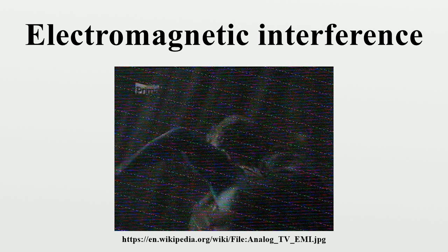Some ICs are designed to have integrated RF filters or a special design that helps reduce any demodulation of the high-frequency carrier. Designers often need to carry out special tests for RF immunity of parts to be used in a system. These tests are often done in an anechoic chamber with a controlled RF environment where the test vectors produce a RF field similar to that produced in an actual environment.